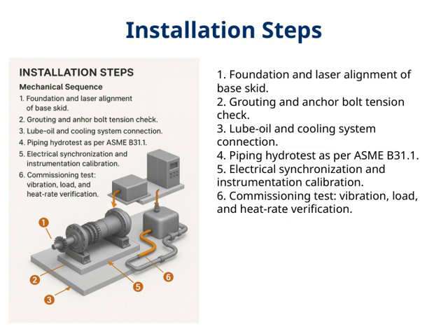Next, we move on to grouting and checking the tension of the anchor bolts. Proper grouting and tensioning ensure the skid is securely anchored and can handle operational stresses. Then, we connect the lube oil and cooling systems. Proper connections here are vital for maintaining optimal equipment functioning and preventing overheating.